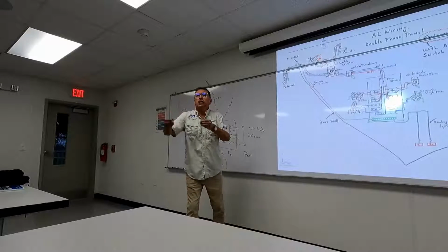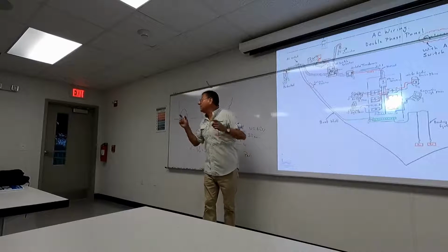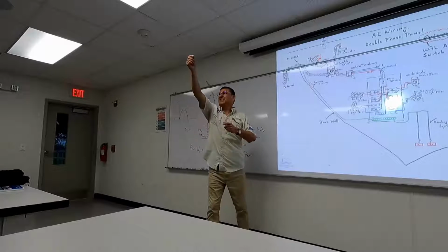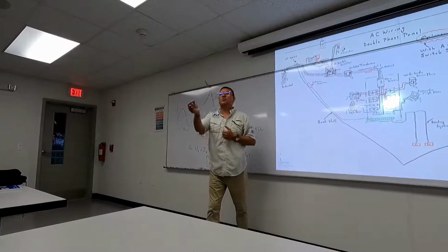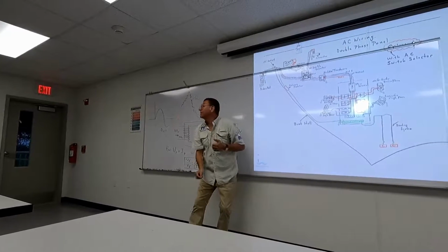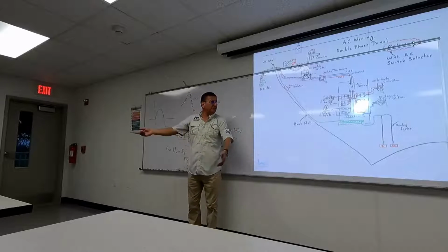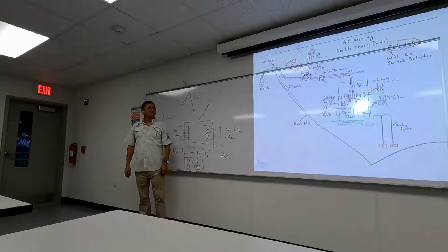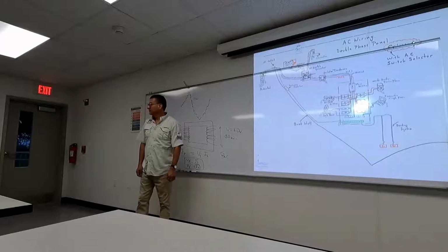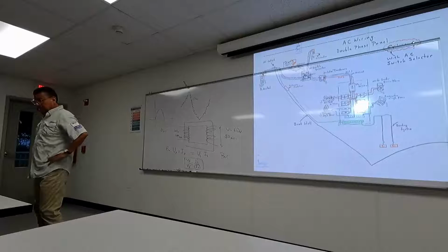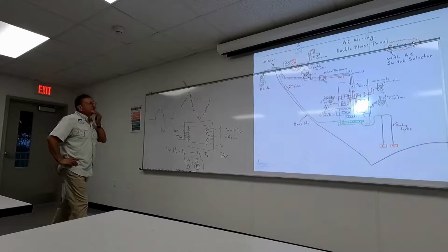The anchor chain, Mr. Lopez, is over there in that corner. I have pictures during the storm. The strike touched the anchor and destroyed the pulpit and the fiberglass because it was not connected to the bonding to drain the current. Where do you connect it? Oh, it's simple. Danny, can you explain? On the anchor itself, it's actually the unit itself. The actual windlass will be bonded. Oh, that's it. If it's all rope, it's impossible to bond the anchor. Yeah. And you can only bond the windlass itself, even if it's chain. What do you do, put a wire as long as the chain? You can't do it, you know.